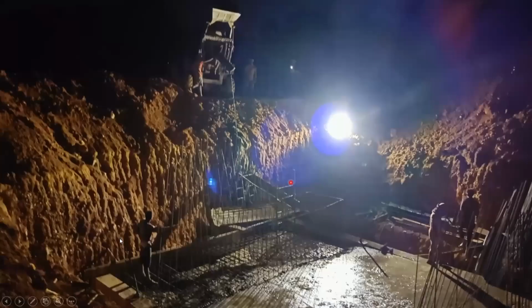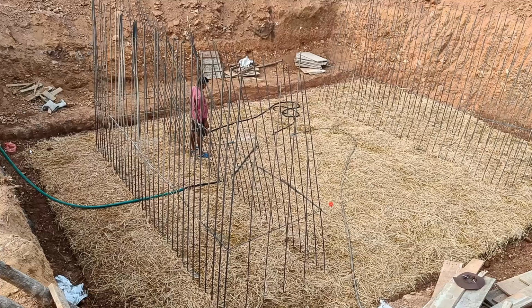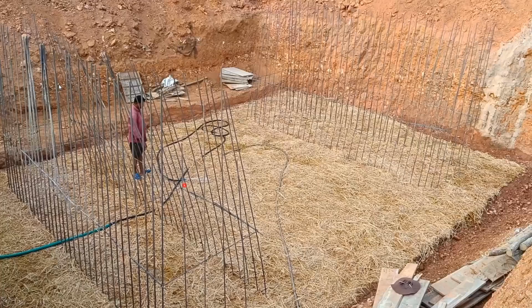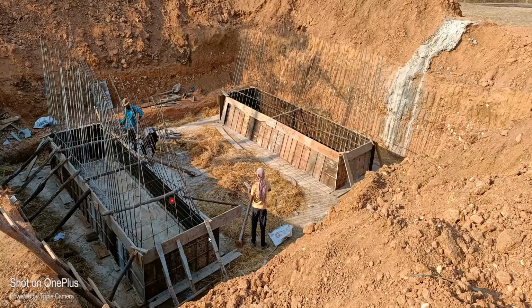Okay, this backfilling we have done, so that is why it looks like this now, this much area. Got it. So once this is done, next we are supposed to do the casting of this abutment and this abutment. You can see again the shuttering will be done for this. We'll not cast the abutment at once, because it's difficult, right?